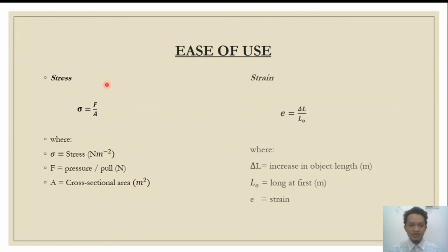The common parameters used in research about the tensile strength of materials are stress and strain, where stress is the reaction that arises in a part of the specimen to withstand the load given, which in mathematical form is force divided by area, and strain is the quotient between the increase in length and the initial length.